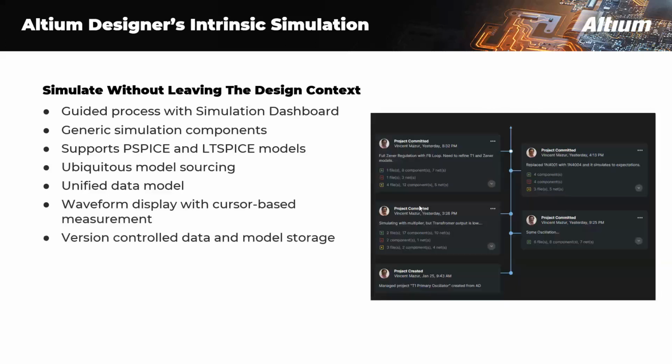Version control assures that designers are always using the current version of a model and provides a way to resolve simulation settings across committed versions. The project history shown here gives you a timeline view of what has been committed, and the changes that were made. Designers can choose to open a snapshot of a commit or revert to a specific commit with a mouse click.